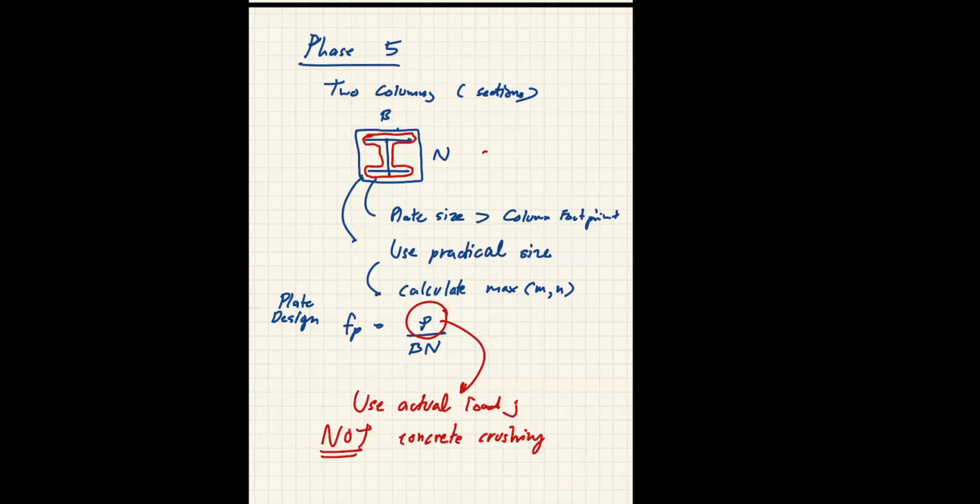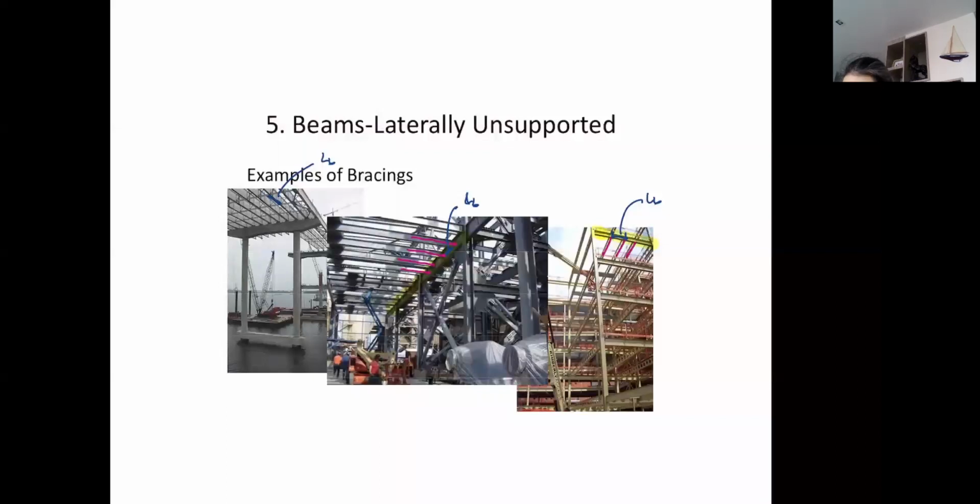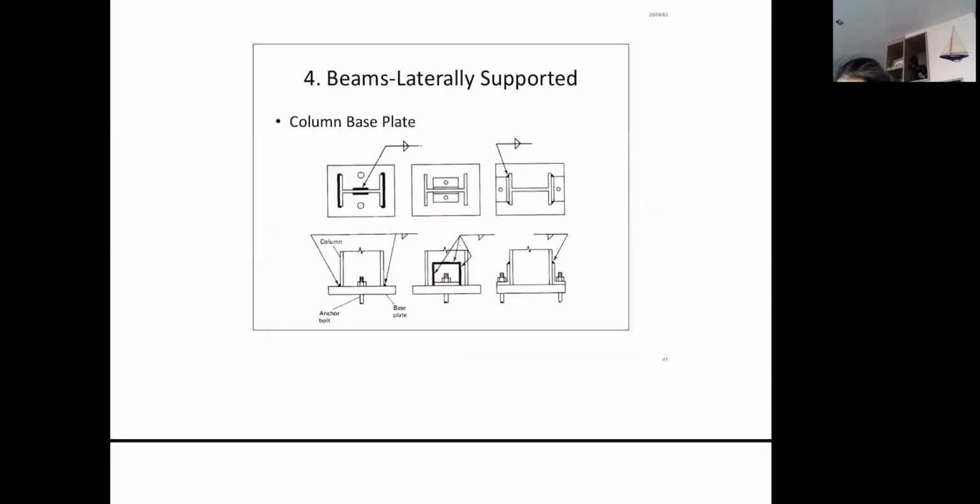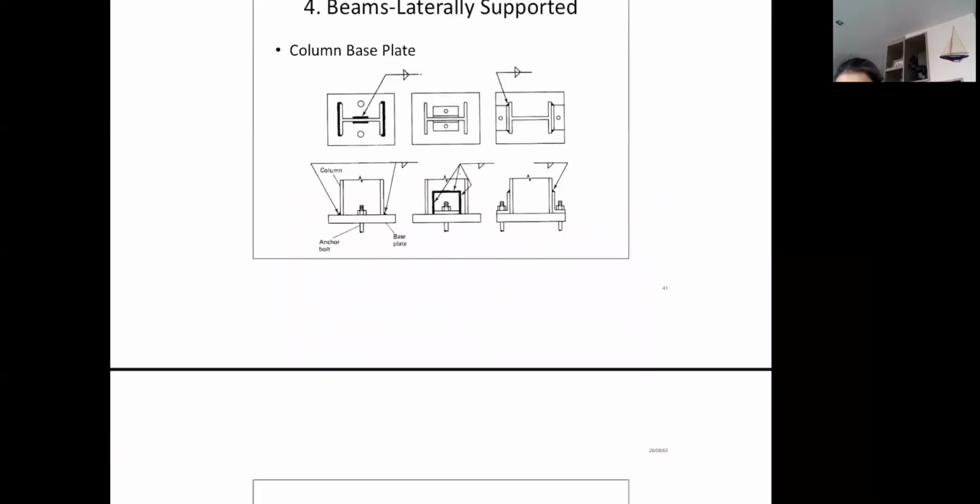That means the anchor bolts will apply for the lower part of the column. We have pictures, I believe, in chapter 4. Generally, the anchor bolts should be set in concrete first, so they are waiting for the column and the base plate to come in.